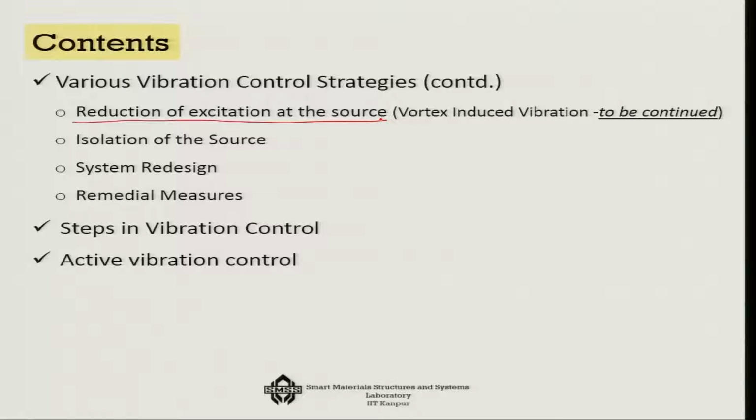In fact, in that category we talked about vortex induced vibration, and I also said how you can use the knowledge of Strouhal number, the relationship between Strouhal number and Reynolds number, and with the help of that, how you can redesign your system. There are also a few more tricks involved with it, which we will be discussing today.